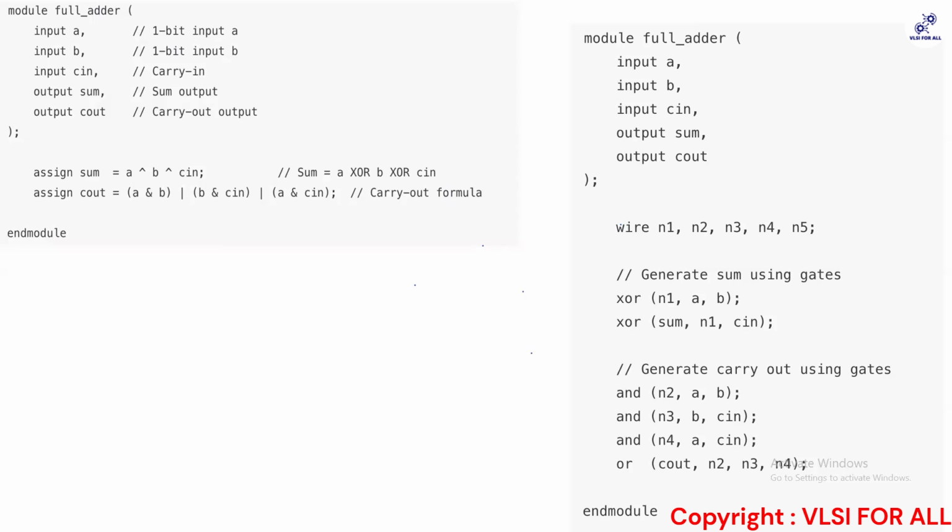But if you had an area constraint, and let us say your library has all the cells, I could have written, instead of XOR here, NAND or NOR gates. Now the tool will understand, the RTL person is saying that I can use NAND or NOR gates. I am smart enough. I know optimization. I can do it using Boolean algebra and everything. In your BTech, you would have done K-mapping, and if you go further, the Quine-McCluskey method. So the tool knows how to do it.